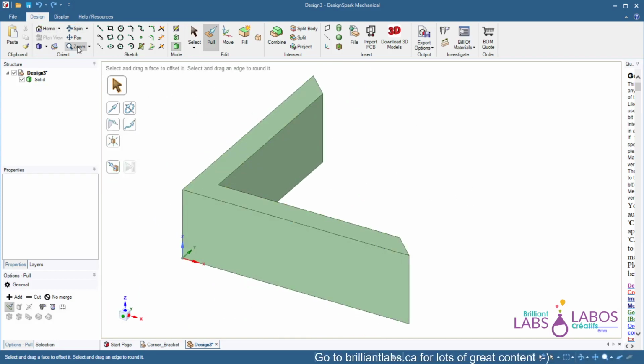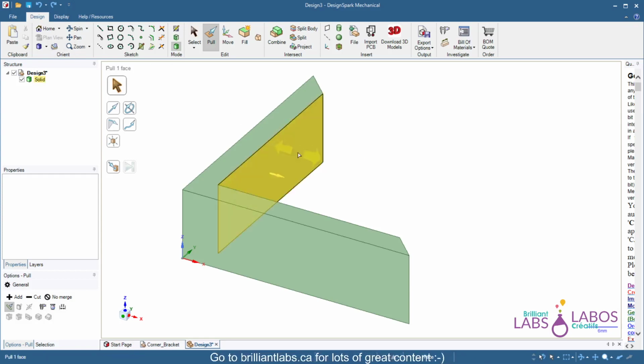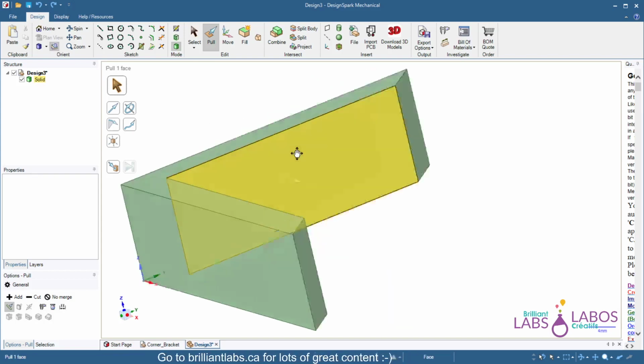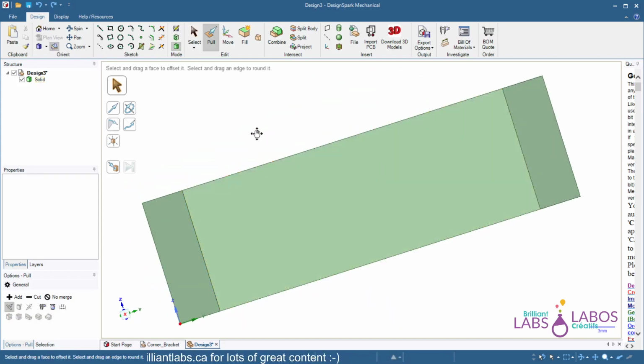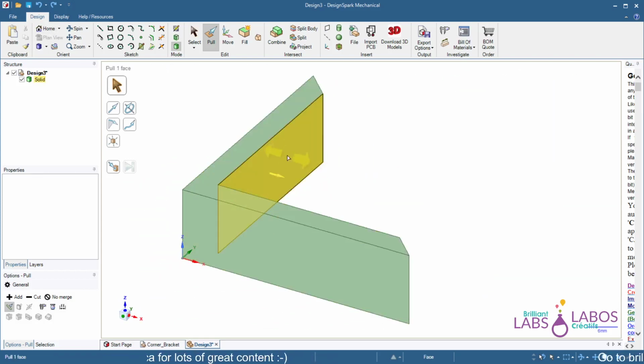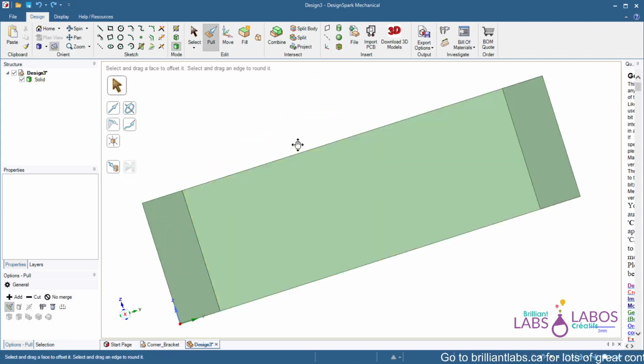We can also zoom in on this one. We can orient it in a particular fashion if we like. For example, that will put us exactly on that face. So let's do that one again. So if I want to draw on here, I can say orient to this one, and it will snap around so I can see this one straight on. So in this view is where we're going to draw a circle that we're going to use as a hole in a bit.